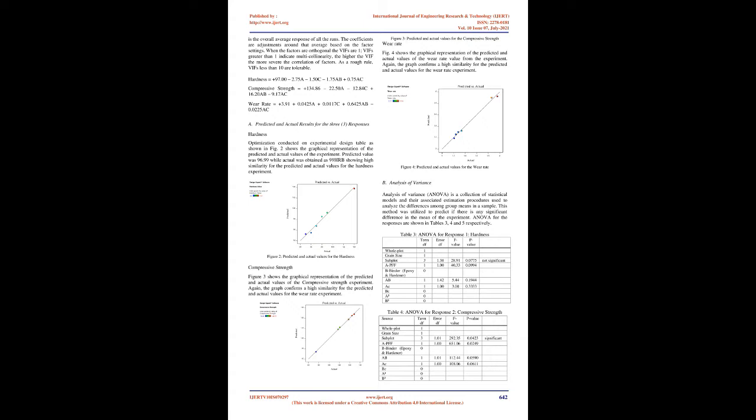The fibers were suspended in a solution of caustic soda, sodium hydroxide, for 24 hours to remove the remnant of red oil left after extraction. The fibers were then washed with water to remove the caustic soda and sun-dried for 1 week. The dried PFFs were ground into powder form using a double grinding mill. Sample formulation. Each of the powdered constituents were weighed and poured in a container. The contents were manually but thoroughly mixed for 15 to 20 minutes to obtain homogeneous mixture.